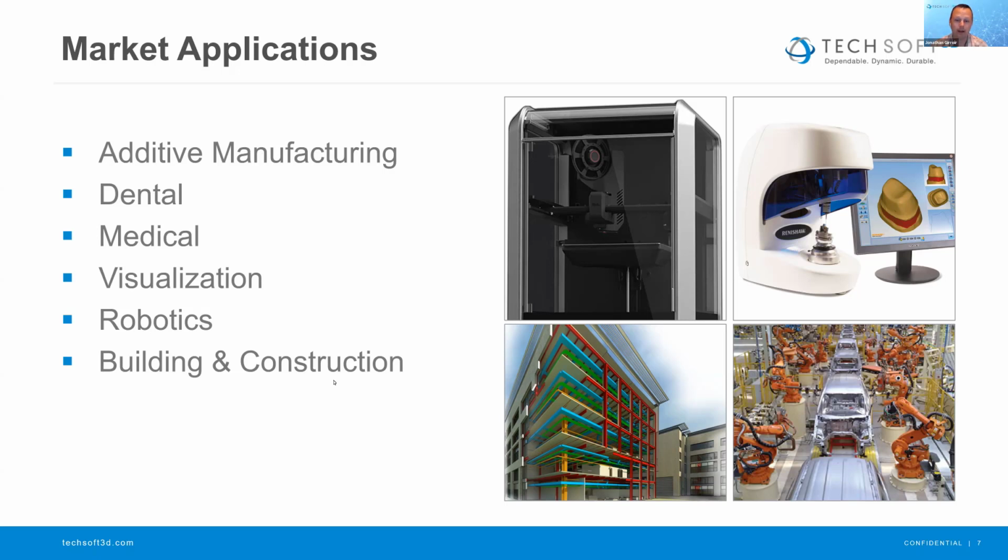The models need to be simplified. Internal objects need to be removed, and there's a process called shrink wrapping that gives you just an exterior shell for a much larger, more complicated model. So again, Polygonica is able to offer that type of functionality for simplifying models, and it works very well into that tool chain and that workflow, being able to prepare models for visualization.